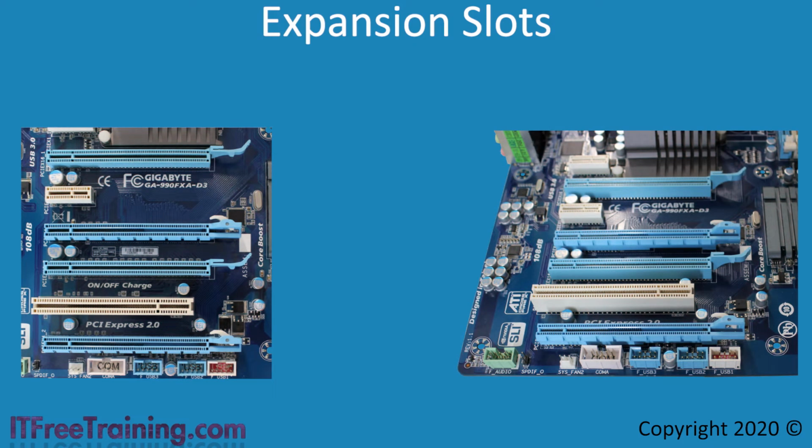Next, I will look at the expansion slots. The expansion slots, as the name suggests, allow the computer's functionality to be expanded. Anything from a video card, sound card, RAID cards, and network cards, to name a few, can be plugged into an expansion slot. The slots are color-coded and keyed. Keying essentially means that only the one connector can be put into the one slot or plug. It is like not being able to put a square peg into a round hole.